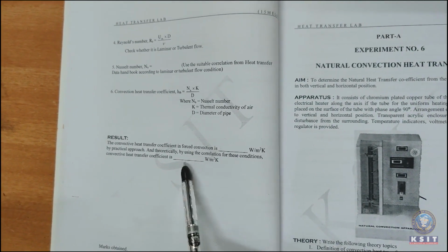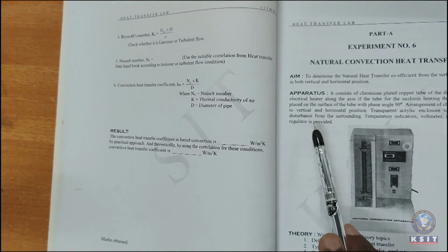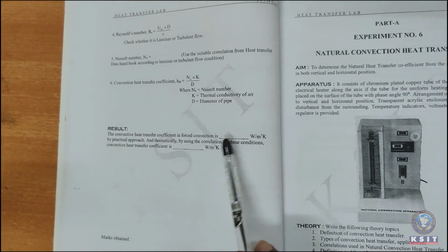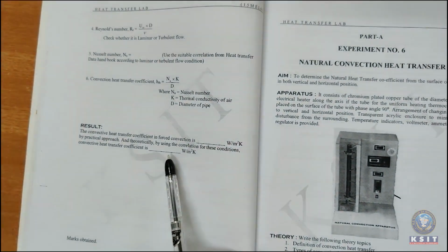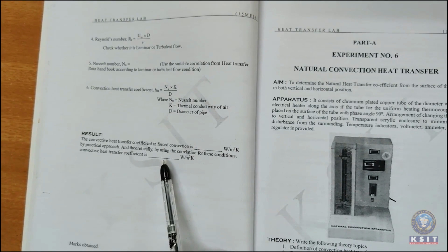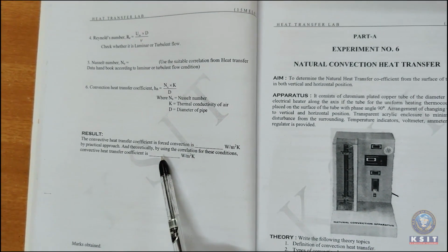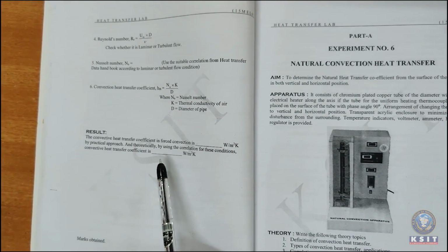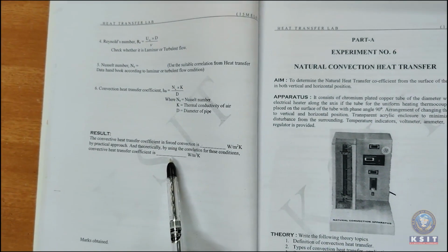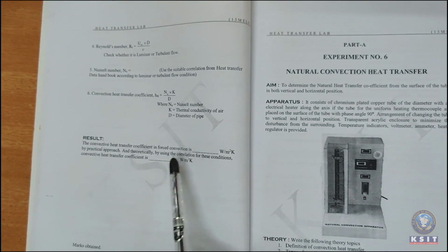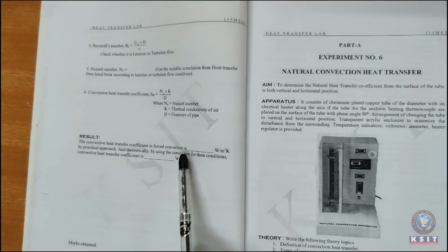These two values will not be the same because there are losses happening in the pipe. The convection happening is not proper, the flow will not always be steady state, and the fluid properties are continuously changing. And there is frictional head loss.